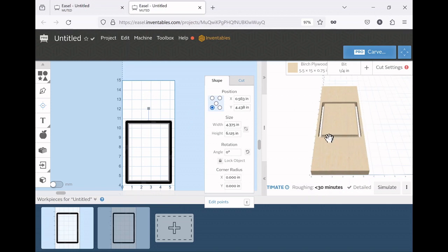If you look closely, you can see the rabbet that we've created by cutting the rectangle number 2 on the shape path. We're actually taking 1/8 of an inch of material off around the cut piece of wood here, and we're going down 1/4 inch with that cut.